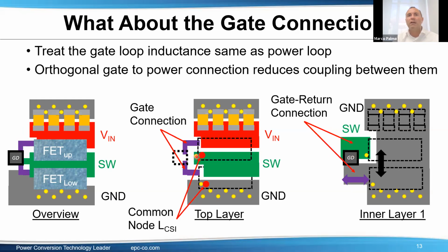That's why you need to connect it in this way. It's the floating ground for the high side, and then if you want to shield the gate driver a little bit, you're going to have this type of via, but that's not really mandatory.